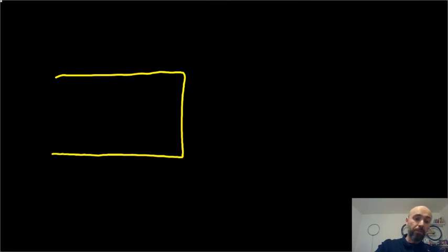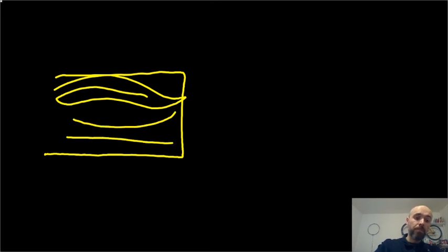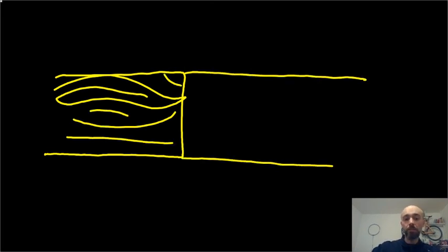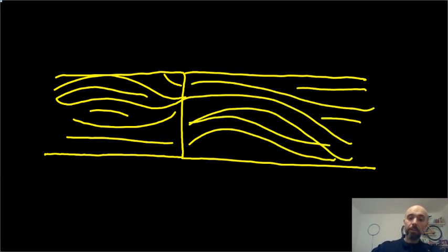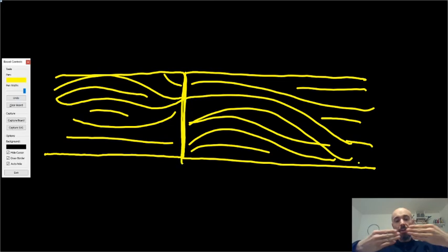So when you have a piece of wood like this with the fibers in this direction, and the next one is glued here with the fibers head to head against head here in this area here. So you have fibers head to head and not side by side. Now the connection in this case is not going to be resistant enough.